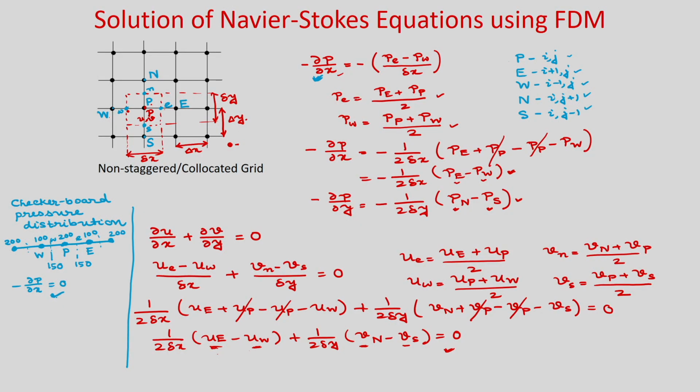So, this is the problem in the collocated grid, and something similar will happen when you have an oscillatory velocity field, and when you invoke the continuity equation, due to this oscillatory field it may be satisfied, but which is not true. So, due to this problem of pressure and velocity decoupling in the collocated grid, we use a staggered grid. In this lecture, when we are using the marker and cell method, we will use a staggered grid.